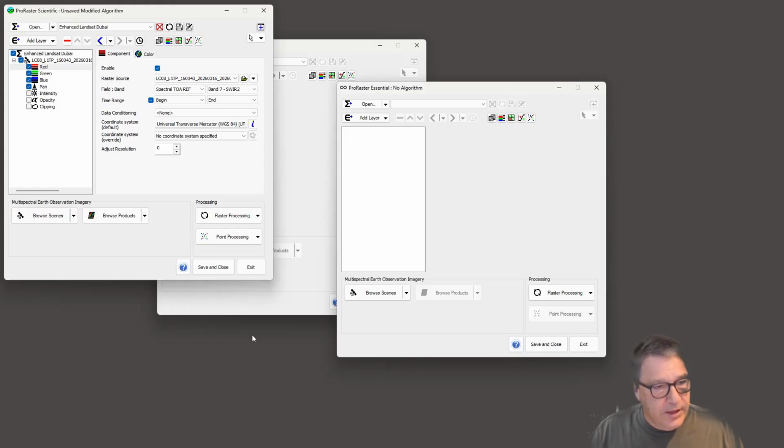So we have nearest neighbor, triangulation and tension minimum curvature gridding algorithms. And for tension minimum curvature, there is also an extension called automated trend reinforcement. And for things like potential field data, like magnetics or gravity data, this provides an extraordinary capability that improves the continuity of trends in your data, and the quality of your output grids is substantially improved.